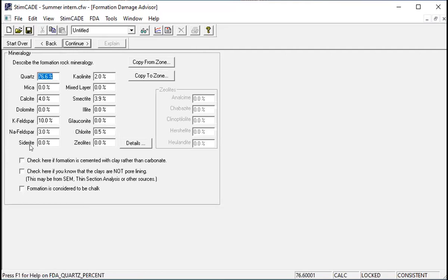So here now you have to input the mineralogy of that particular reservoir, because the mineralogy will give us a clue about what type of acid we are supposed to use. Some acid will not work in a particular milieu while it will work in others. If I have a system that has no clay, then there is no way I should be thinking of fines migration. Even though we could have silt, most of the time fines migration is as a result of clay, particularly smectites.